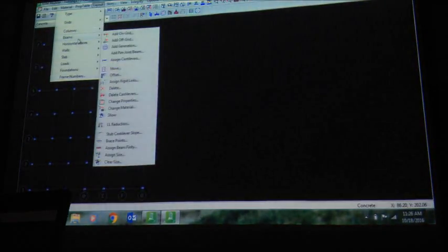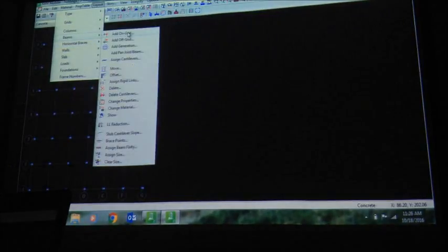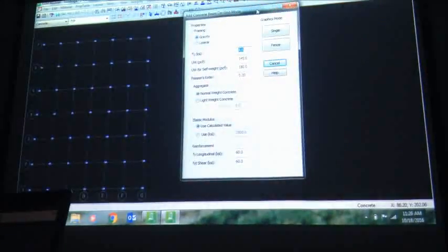Okay, I want to give now a little bit on the beams. Next item is beam. Again, my beams are what? From column to column. So I will say add on grids. Gravity and things, these are all almost same. What I will do is again single first. And if you see, it snaps on the column to column.